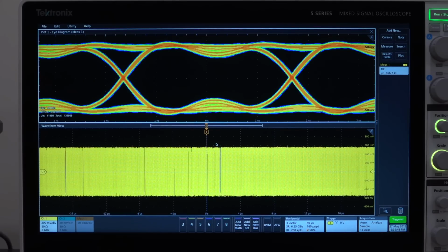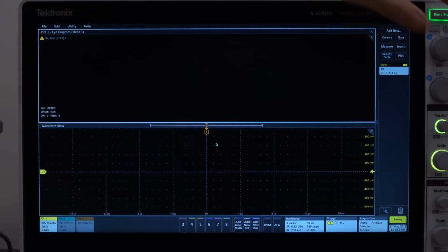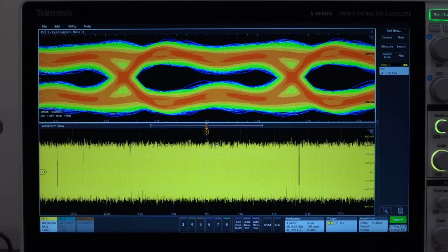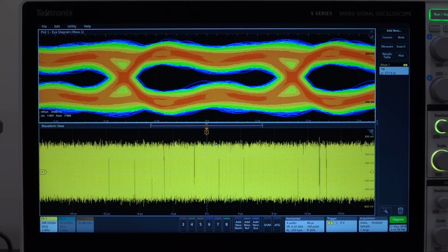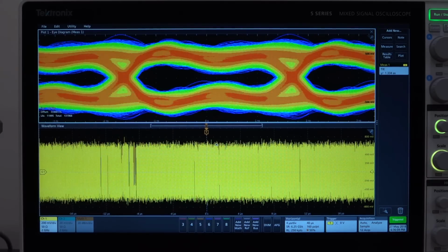So I'm adding it from the second channel by doing waveform combine, and here it is. Let's clear this so we can see it from the beginning. And here we go, and take a look. This eye diagram now has significant imperfections on it, major amplitude noise, major jitter, and the eye opening has this weird peanut shape to it.